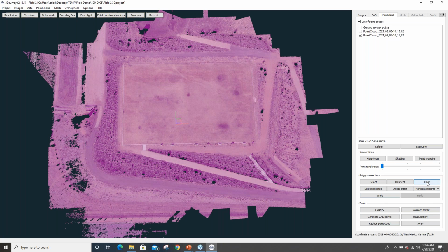All right, I'm gonna do something else here to kind of clean this up. You can see that some of these outlying areas end up with data that is not quite complete. That's because as a drone flies around, there's data that we don't have pictures of, or don't have a lot of pictures of, and that's normal with drone surveying. In the field, I'm gonna wanna make sure that I get a buffer around the area I want to fly so that the area that I want to focus on is well covered. And in this case, I was just focusing on the field, so this is fine.